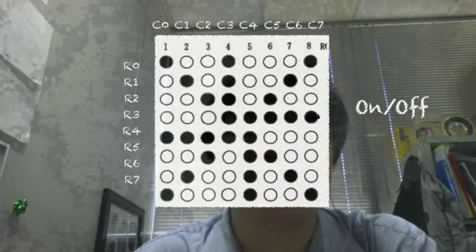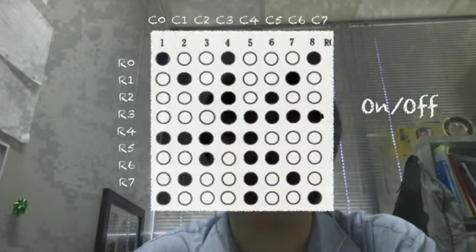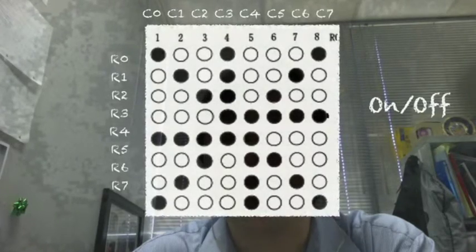Still, 17 or 18 lines is too much for us because our board contains only about 13 I/O pins, or if you use the analog lines, maybe you get an additional 8 I/O pins. But we don't want to waste them all on the LED. You still need them for something else. Here's another idea. What if we only want one pin of the 8 lines to be on at a time?